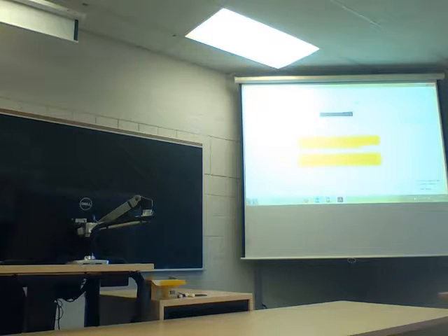Figure 7 shows a 3-stage tandem compressor design in which the first stage cylinder is double acting, while the second and third stage are single acting. The result is almost evenly divided loads between the outward and the return. So remember that they're real smooth, all right? Because we're doing the same, it's not like a chugga, it's actually nice and smooth back and forth, because we're pretty well balanced.